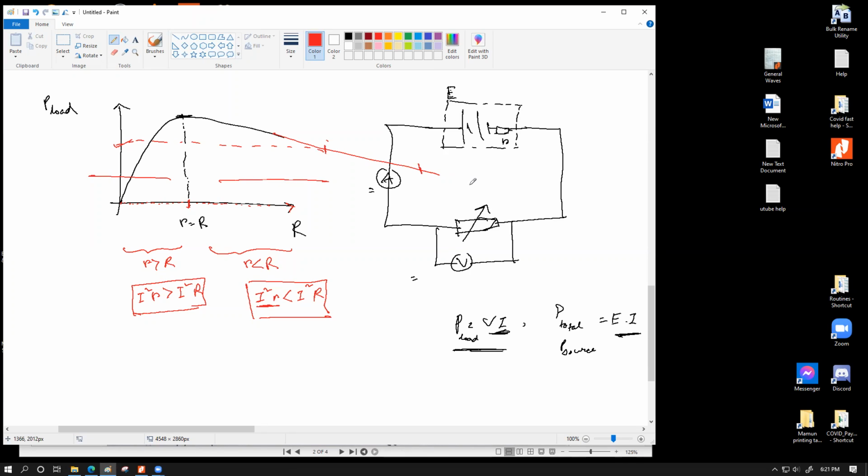However, if you think of a handheld drill, a battery powered drill machine, or a battery powered screwdriver, then you can also choose to be somewhere over here, because with those handheld drill machines, you're not going to run them continuously. You're going to make a drill, put down your drill machine, do the necessary installation over here, and then pick up the drill and do another drill over here. So there are intermittent gaps, and within that gap, the battery can cool down. So in that case, you can choose to have a higher load power, so that you can have a stronger torque on your motor. So it is an application specific choice. Does it make sense?